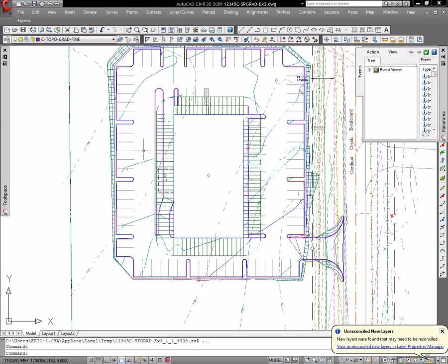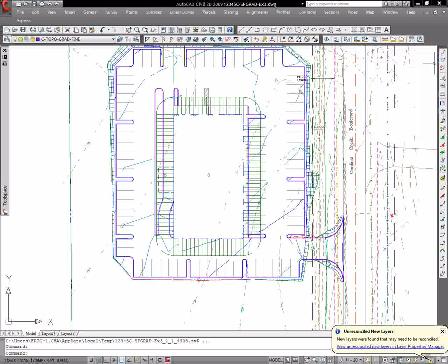It's pretty flat here, and then it starts to drop down more steeply to follow what we've done with the island curb elevations. So what we'd like to do is kind of straighten this back out so that our parking lot grading is a nice, smooth, constant grade the whole way from north to south. So we're just going to use our set grade slope between points command once again,